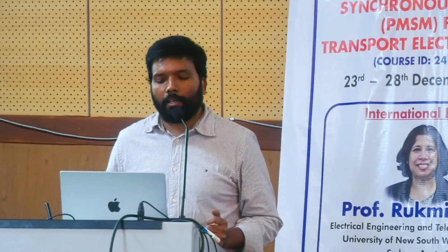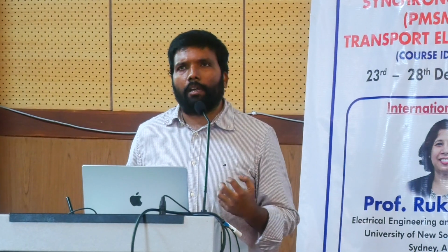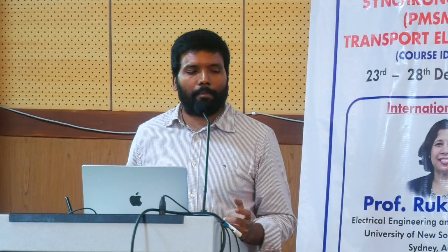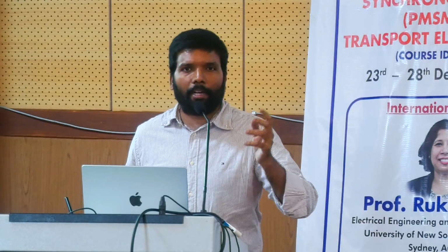See, if you take a three-phase system, what is the nature of the resultant MMF? Resultant MMF is rotating in nature. If MMF is rotating, you can assume that MMF is a function of the current only. Net current is also rotating. But mathematically, if you verify, if you add A phase, B phase, C phase current, net current becomes 0. If net current is 0, it means that net MMF is also 0, right?